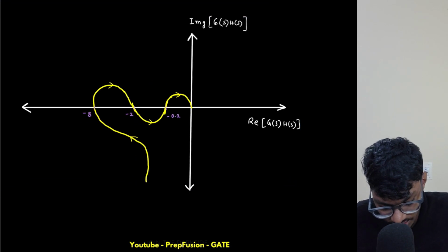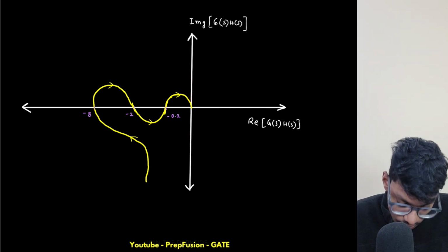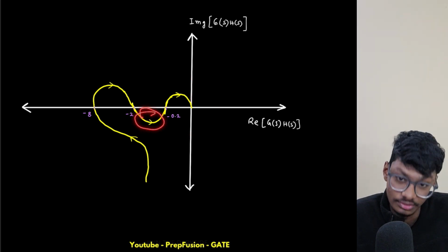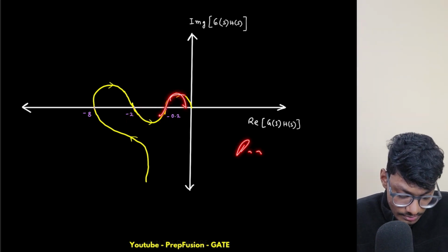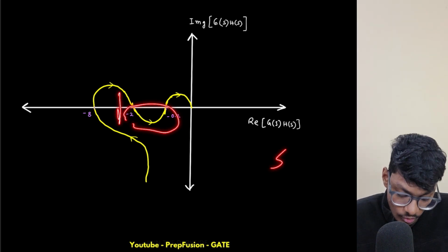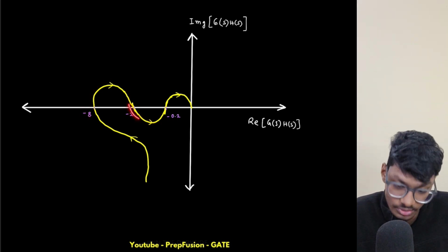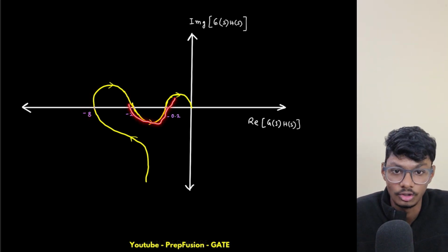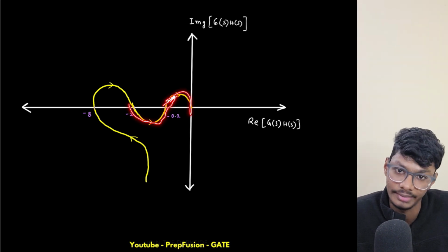What I can observe is, again, a type 1 order 3 system, right? There are zeros also here, but at the end p minus z becomes 3 only. This zero is contributing some positive angle. As I explained in the polar plot, if there is a zero, it contributes some positive angle, then the dominance of the zero is over and the pole again dominates. Hence we are ending at minus 270.